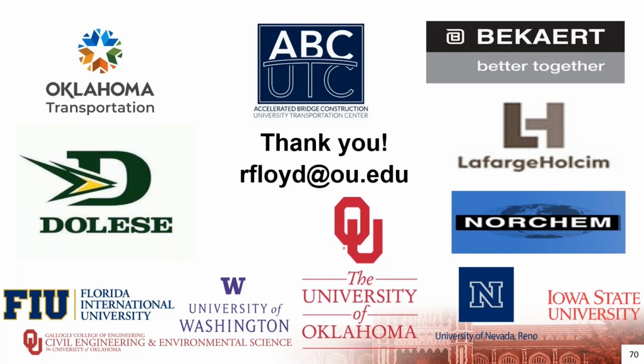Does a non-proprietary mix design need to be modified for locally found materials? Potentially. One of the things that we found specifically is that the materials available in different locations do behave a little differently, especially related to flowability or, we'll say, high range water reducer demand. So it's very important to at least do some trial batches with the locally available materials to ensure that you're going to get the performance that you're anticipating.